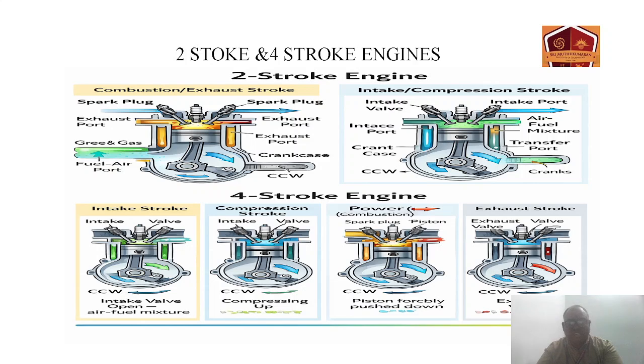The power is more, but there is partial combustion. That's why we get oil droplets settling in the muffler, but the combustion process takes place. The pickup, when compared to four-stroke, is more, because all the cycles are completed in one revolution of the crank: suction, compression, power, exhaust.